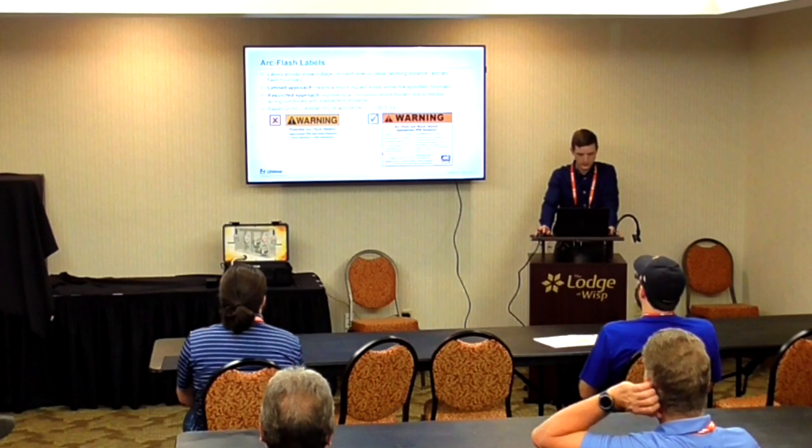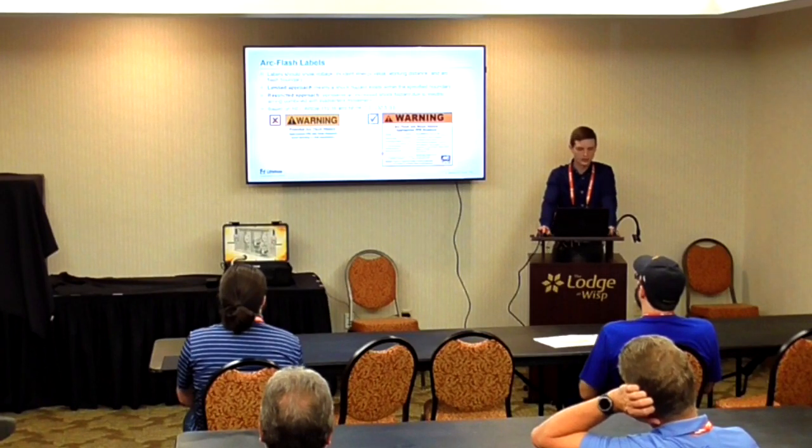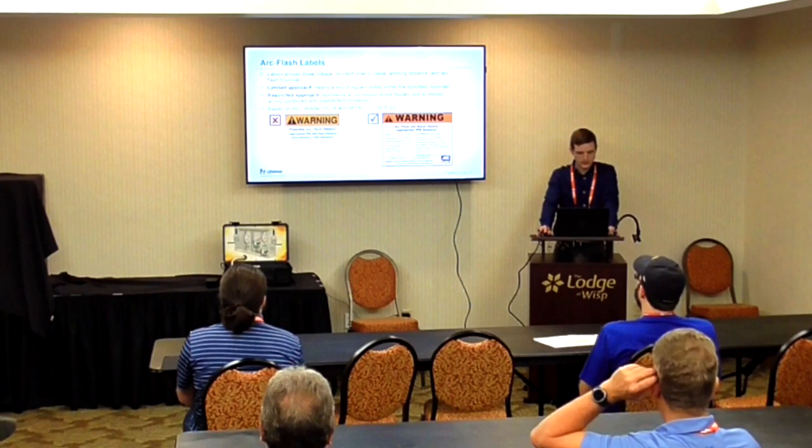You'll see the value for the restricted approach is typically much, much closer. You're actually working on the equipment, and your limited approach is a little bit further away, so if somebody has to get some tools ready or anything like that. This is that 110.16 in the NFPA 70E.